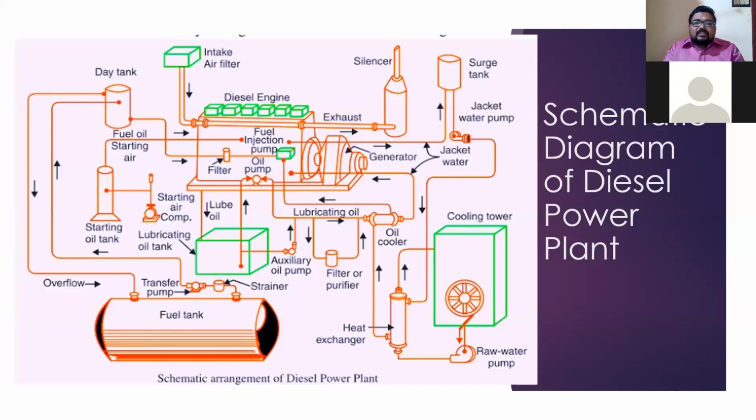If the temperature rises beyond the limit of the lubricating oil, then it won't perform its function, and the burning of your lubricating oil will happen. To avoid that, before entering the diesel engine, it should be cooled properly. That is why the cooling happens, and then the lubricating oil goes into your diesel power plant.